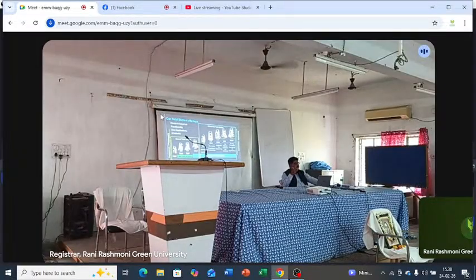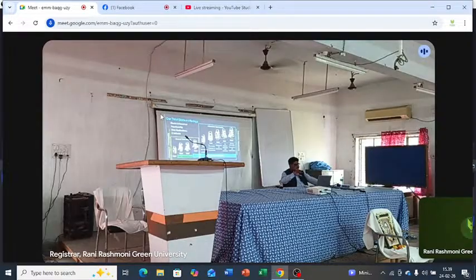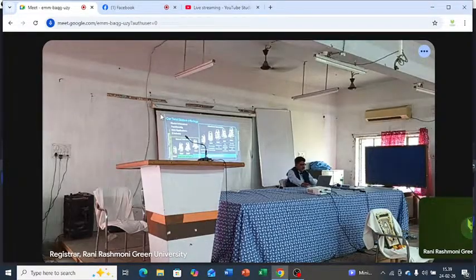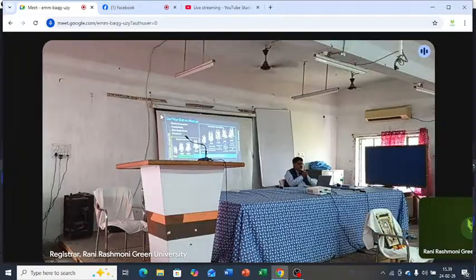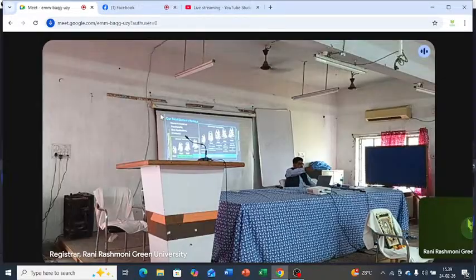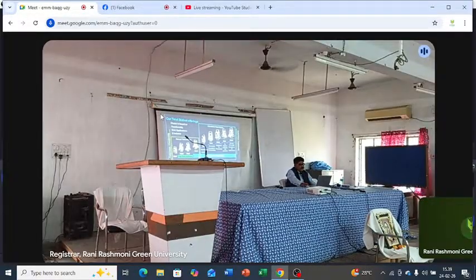MS is a multi-station. It has some other functionalities and total station. We'll cover all of them in the course of time. There are two more differences between these two. One is a multi-person survey. In manual total station, a surveyor has to be behind the instrument, and a survey crew will be carrying the prism on the rod to the object. So there will be at least 2 men required. So it's a multi-crew unit.